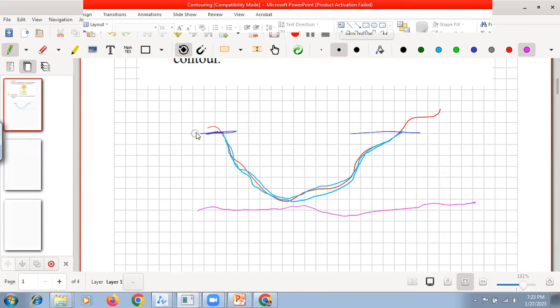Then what we do? We will mark these levels on the wall, and from there, with the help of the measuring tape, we will measure the distances. If this distance is, say, 2 meter, and this distance is 2.1 meter, that means this is not in a perfect level and it has a slope of 0.1 meter towards this. Or if you measure this distance, it may be 2.2. So there is undulation at this particular point.